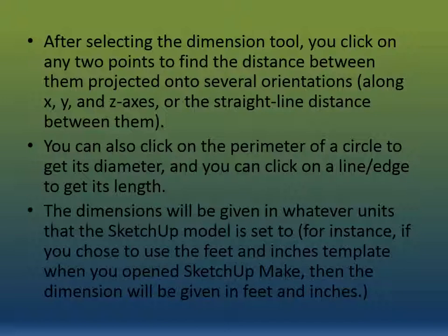The dimensions will be given in whatever units the SketchUp model is set to. So if you chose the feet and inches template when you open SketchUp Make and start building your model, then the dimensions it shows you will be in feet and inches. Or if you use meters and millimeters, then the dimensions will be in meters and millimeters.